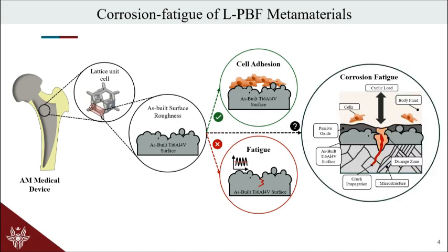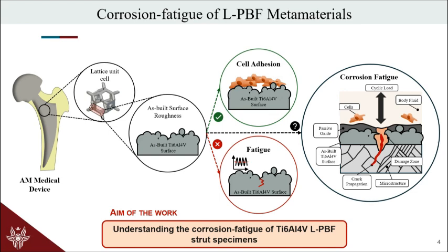But one thing which is often overlooked is the corrosion behavior, since this kind of implant is designed to be implanted in a specific body fluid with corrosive ions and a corrosive environment. And so this is basically the aim of this presentation and of this work: trying to understand the fatigue behavior of Ti64 laser powder bed fusion strut specimens or metamaterials, particularly considering the role that these defects and the enhanced as-built surface roughness have and how they might impact the corrosion fatigue behavior.